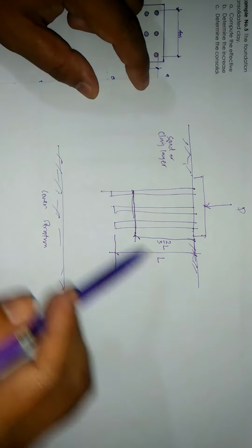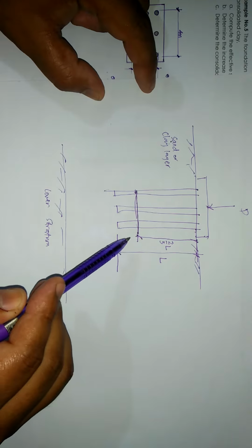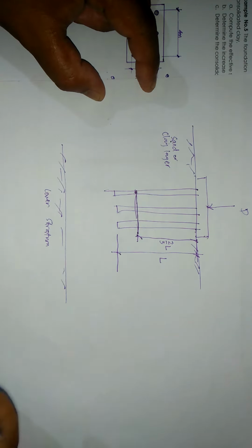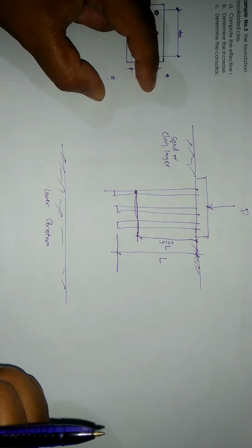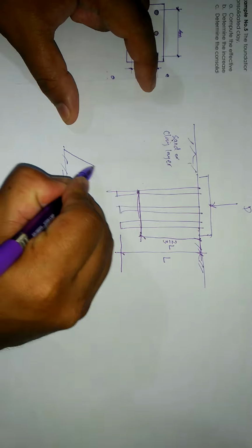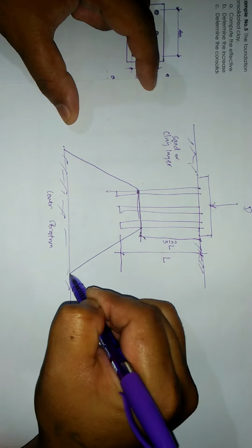But below the 2/3 of L depth, the pressure distribution spreads out at a vertical to horizontal rate of 2:1, parang sa previous example.